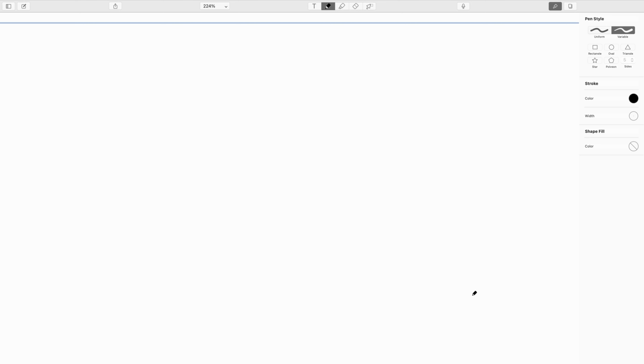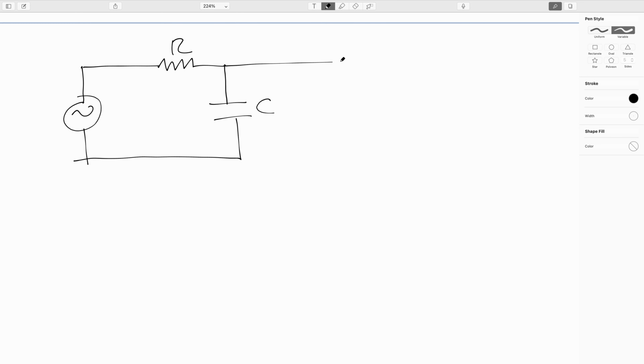So what you'll do is you'll design a crossover. So your stereo source here will be providing AC electric that's heading off to the speaker. And let's say this is going to the subwoofer. What they'll often do is somewhere in the amplifier cabinet, they'll have an RC circuit like this, and then they will send these leads here off to the speaker.